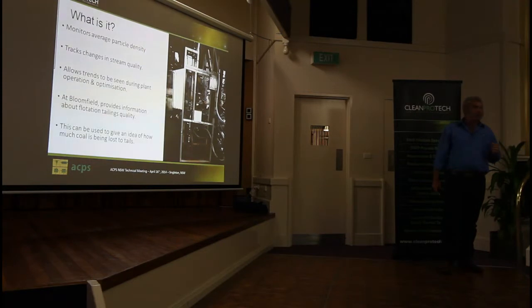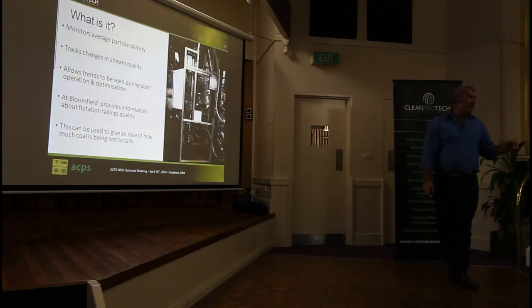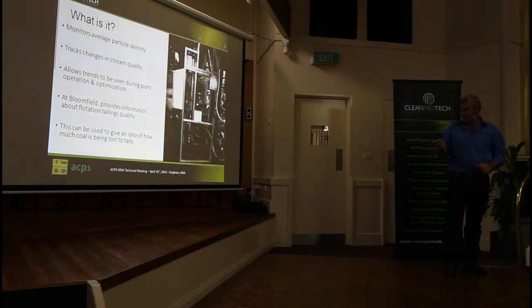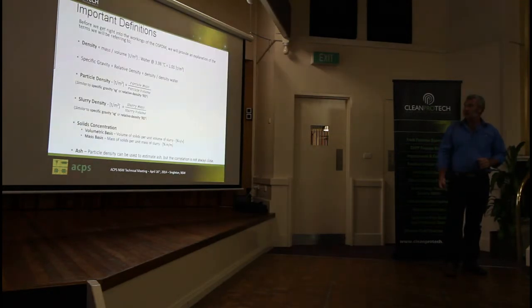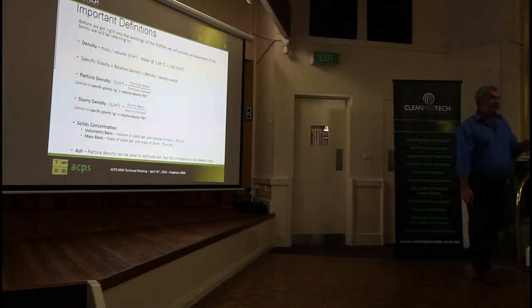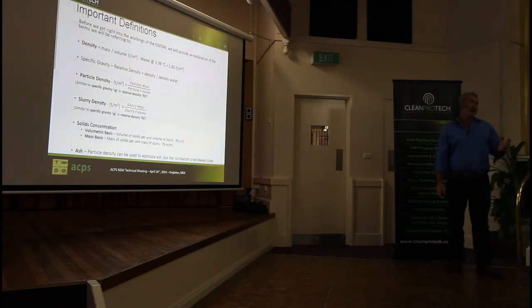At Bloomfield, we've got it in the tailing stream, and the beauty of this thing is you can make any change you want to the flotation and you just see the response in the tailings particle density immediately. Okay? And of course that gives you an idea of how much coal is lost to tailings online. I will go back to a couple of other things about the OSPDM.